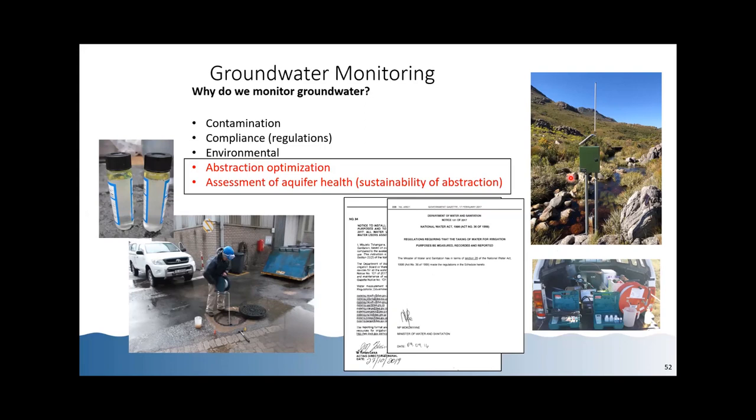But really, in the 10 minutes that I've got with you, I want to demonstrate how groundwater monitoring can benefit you as the groundwater user. And it really goes around optimizing your abstraction. By that, I mean making the incremental changes to your abstraction, the volume that you're pumping, to ensure that firstly, your usage is sustainable, that your bore is going to continue to supply you in the years to come. But secondly, that you're using it to its optimal capacity.